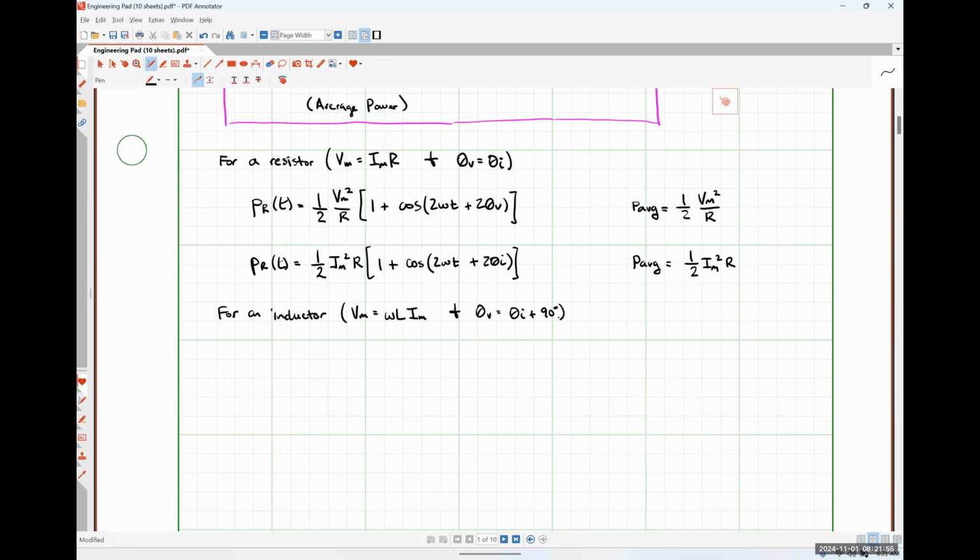So the current is always lagging the voltage by exactly 90 degrees. You guys probably found something close to that relationship in our lab on Wednesday. You wouldn't get exactly 90 degrees because we don't have an ideal resistance, or excuse me, an ideal inductance. So the resistance of the coil itself, the wire in the coil itself, is going to push that a little bit away from 90, but it shouldn't have been huge. So if you did everything correctly, it should have come out to be somewhere in the ballpark of 80 to 85 degrees.